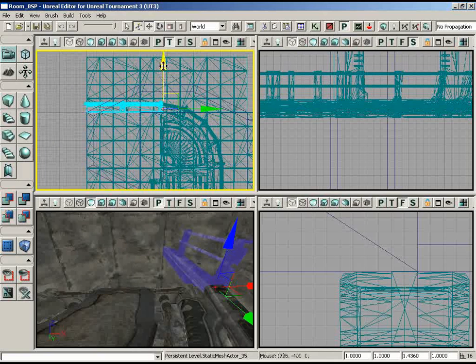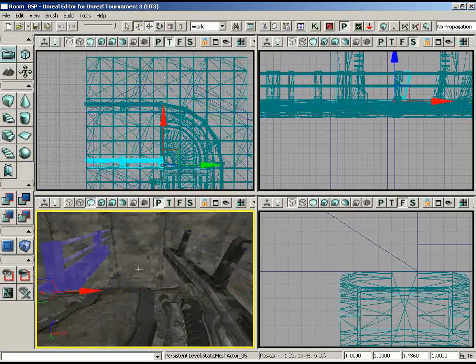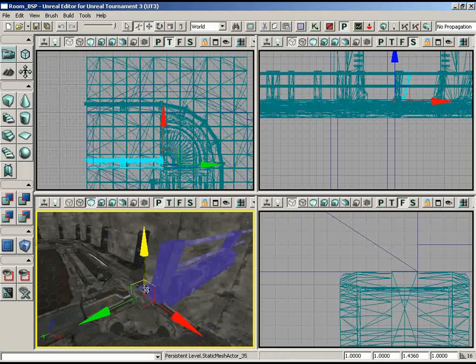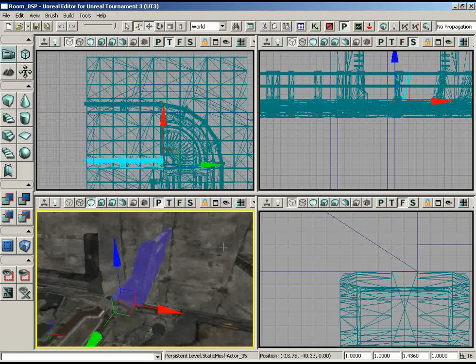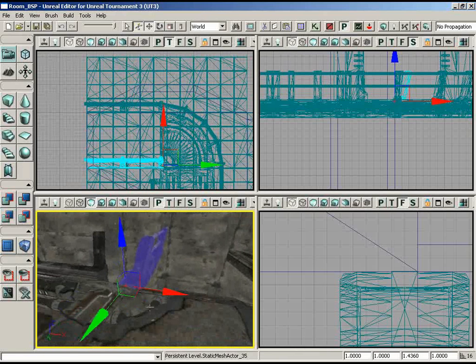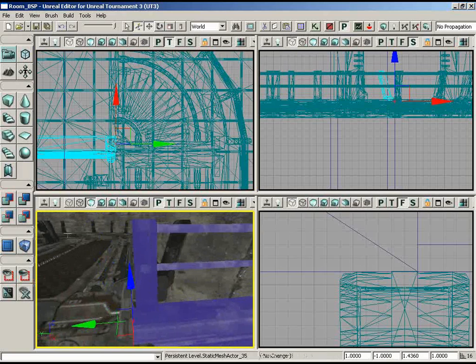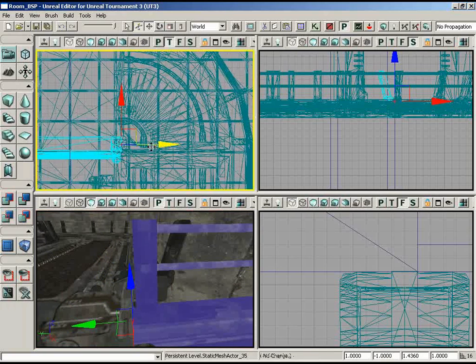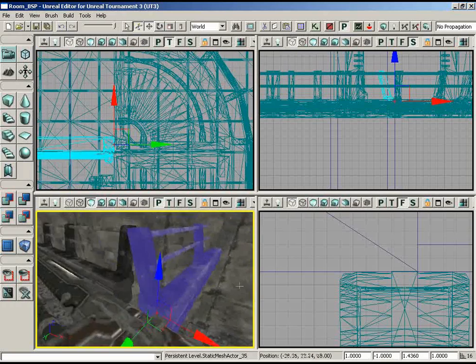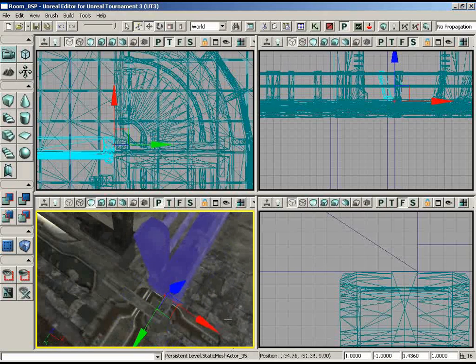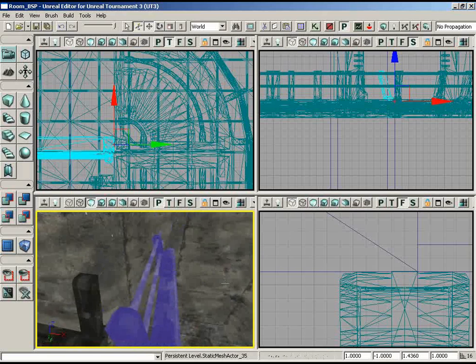And let me duplicate it over down here. Now I don't want to rotate it because I like having the pivot basing the positioning on this side. So instead of rotating it 180 degrees, I could grab draw scale in X and set that to -1 and just mirror it instead. That way I retain my positioning on this side. And let me find a good place to snap this into, because I kind of need to come up with more of a corner alignment here. Let me look at it this way.